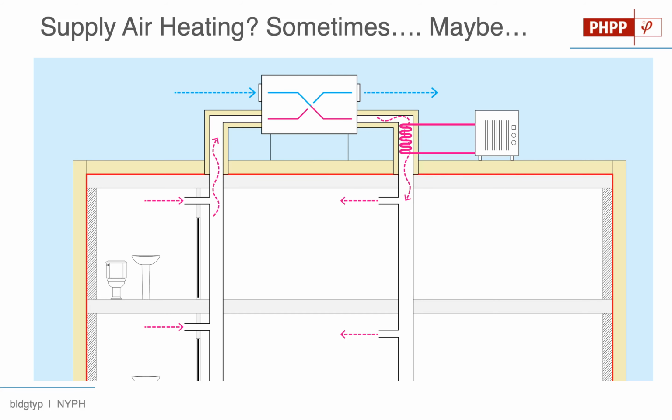Well, of course, I'm sure you all remember from your passive house training that the original idea behind what a passive house was and how it was supposed to operate was that it wouldn't have an active heating system per se. Instead, it would have a ventilation system, an ERV or an HRV, and then you might have a simple post heater, which would add some heat to that ventilation airstream, and you would supply all the heating needed for the building riding on the ventilation air.